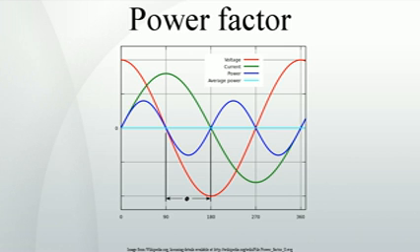If a load had a capacitive value, inductors, also known as reactors in this context, are connected to correct the power factor. In the electricity industry, inductors are said to consume reactive power and capacitors are said to supply it, even though the energy is just moving back and forth on each AC cycle.